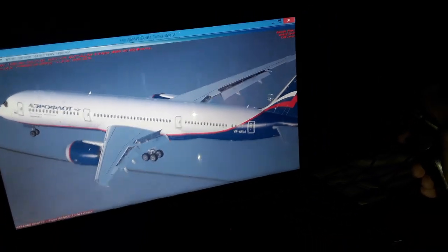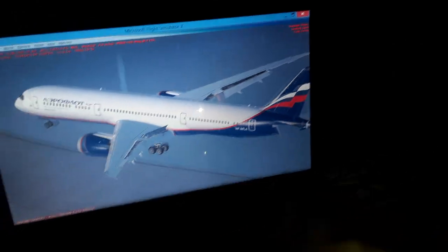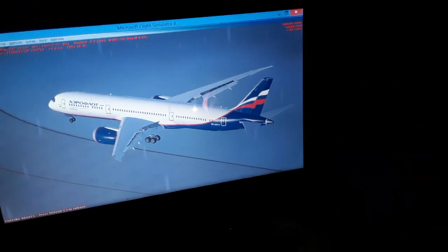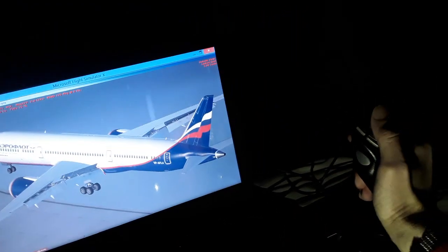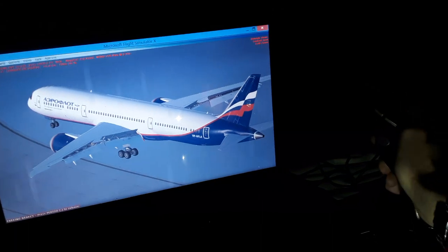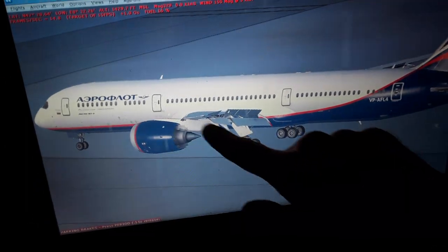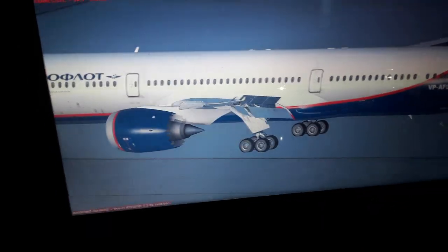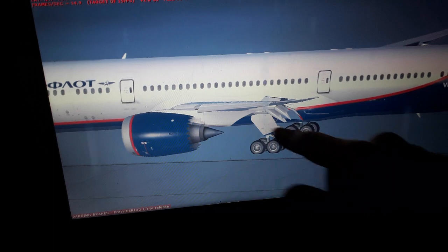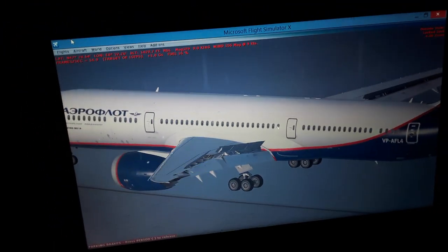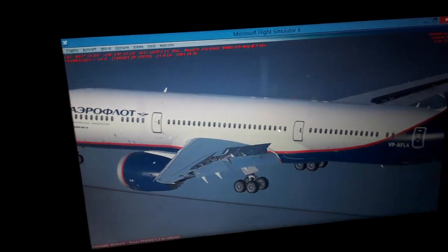So we have the longitudinal axis, and the horizontal tail forces affect the moment arm through the center of gravity for climb and descent, and also the thrust levers. And also we have the bottom surface of the wings. You can see here, using Bernoulli's principle, it is more flat. So as we accelerate for takeoff, the airflow has a lower speed below the wings, which creates higher pressure below the wings, which pushes the aircraft weight and wings up into the air.